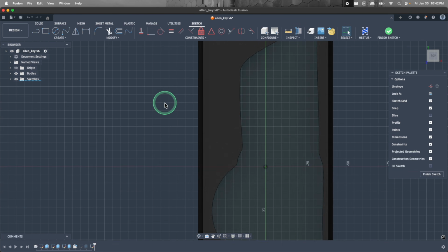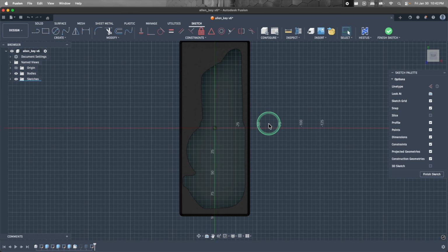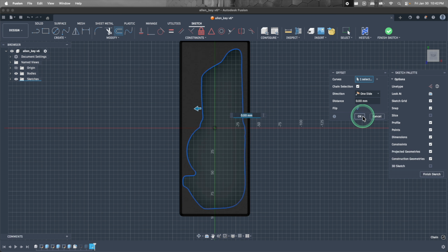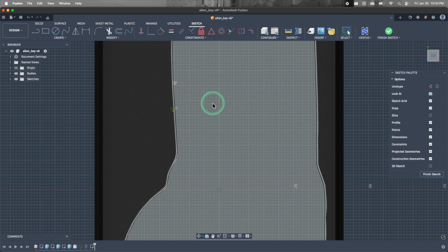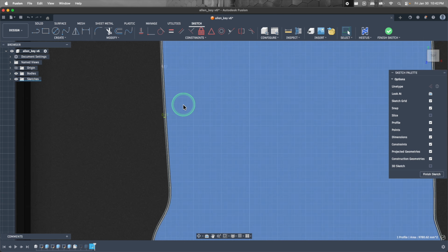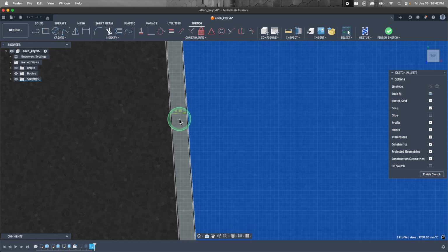Simply start a sketch on the top face of the bottom of the extruded cutout, then use your project tool by hitting the P hotkey to project the entire perimeter of that face. Next, use your offset tool and select your projected sketch. I would recommend offsetting at least 0.4 millimeters or so to make sure the insert fits properly into your bin. This can vary depending on the complexity of your cutout. Feel free to test out sizing as needed to get it just right.